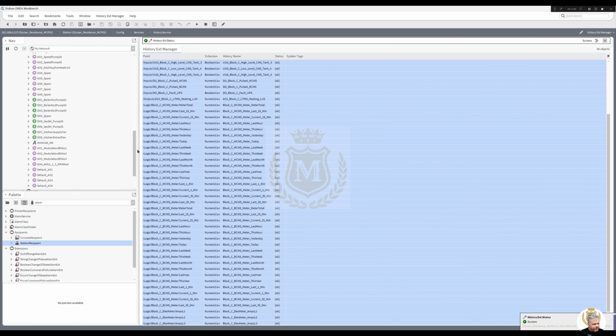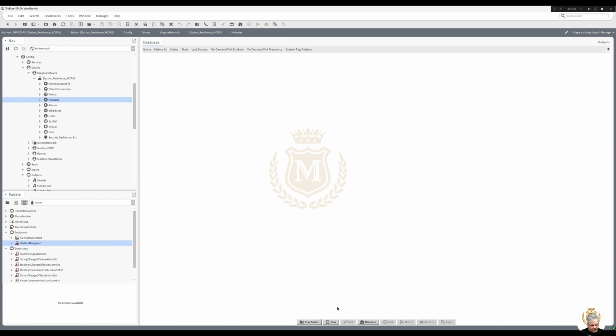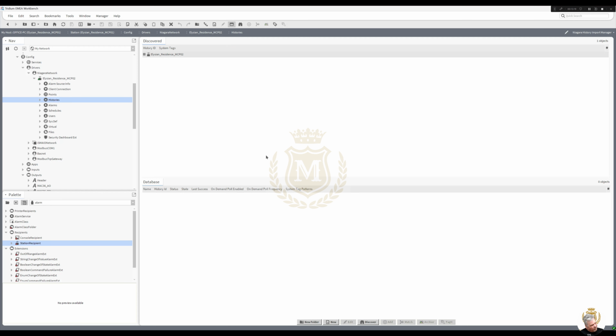Minimize MCP2. Go back to our MCP1 Niagara network, Niagara network MCP2, but we're on MCP1 station. Histories, discover. Now this is going to talk via normal Ethernet network, so I think what we'll do is we'll do the histories talking to the station, I don't know, every 15 minutes.